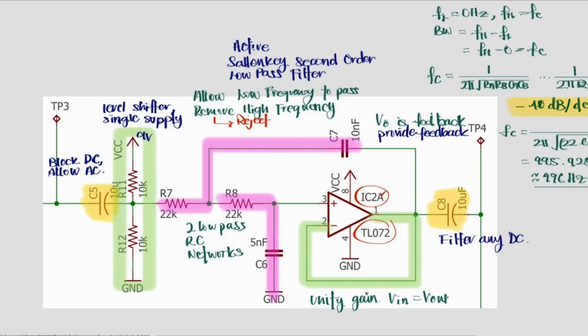The low-pass filter in stage 3 is set to be around 996 Hz because it allows all useful heartbeat frequencies to pass through clearly while filtering out unwanted high-frequency noise. This cutoff is practical as it uses standard component values, ensures circuit stability, and maintains the clarity of the heart sounds without attenuation. C8 is a coupling capacitor again that connects this stage to the next, blocking DC signals and allowing only AC to pass.